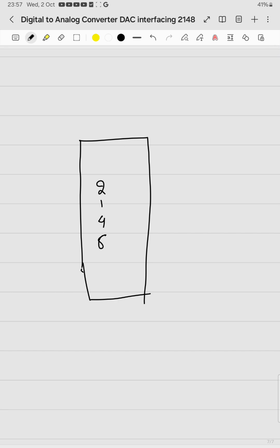There you have to take pin number 9 and put it to the CRO or DSO, and on the CRO you will be able to see the square wave of 50% duty cycle, and then you just measure the frequency of that waveform.